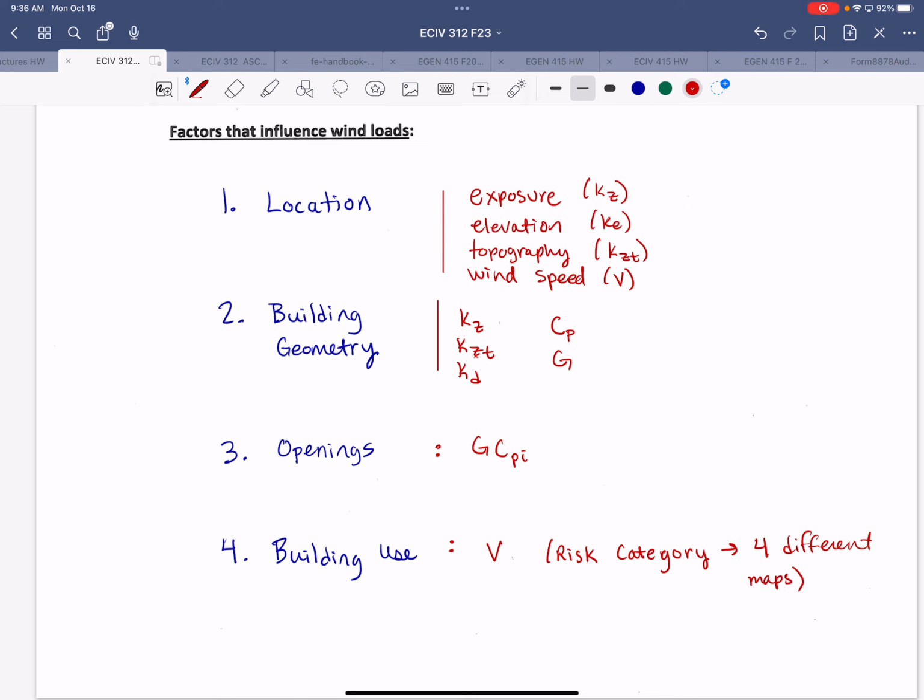So you can see there are just entire blocks that were destroyed. And so that's one unique thing about tornadoes, they can be very site specific. So in some neighborhoods you'll see one house is totally destroyed and another house is intact and then another house is totally destroyed. And some of that can have to do also with how well those houses are connected together. Of particular importance is the connection between the roof and the walls and then the walls and the foundation. So if they're not tied down properly, those elements can just be ripped off by strong winds.